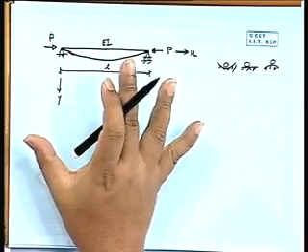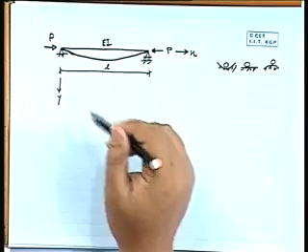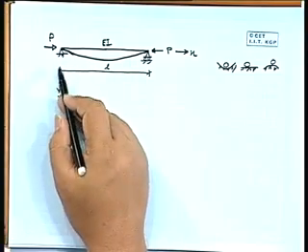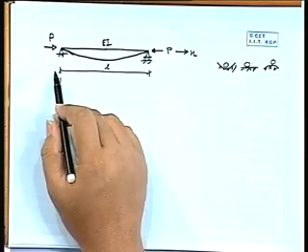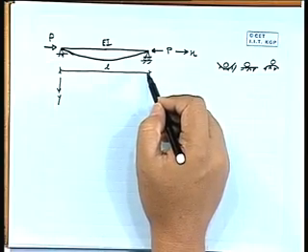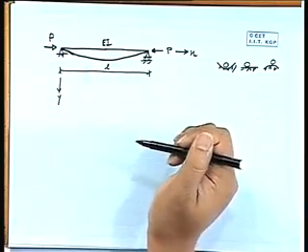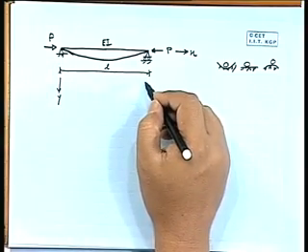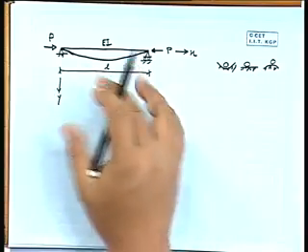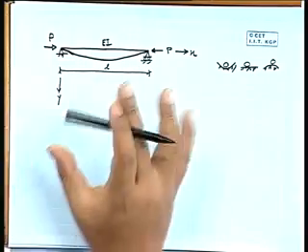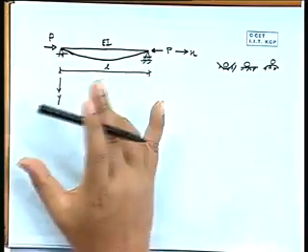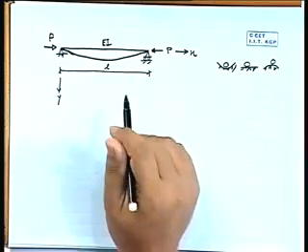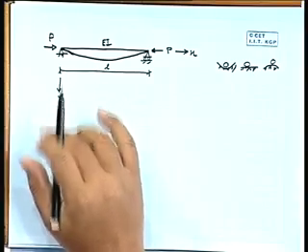There will be no vertical reaction because both ends are simply supported. So there will be no moment there. Now, if there is a reaction here, it should be balanced by the opposite reaction because there is no applied load. So if it is some R, it will be minus R. So the force part will be balanced, but they will create a moment. There is no applied moment, so automatically those forces should be equal to 0. From there we can get the idea that there will be no vertical reaction here.